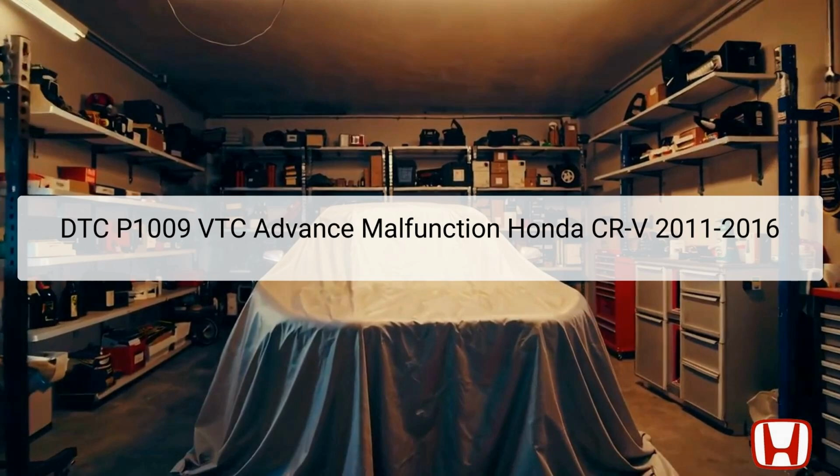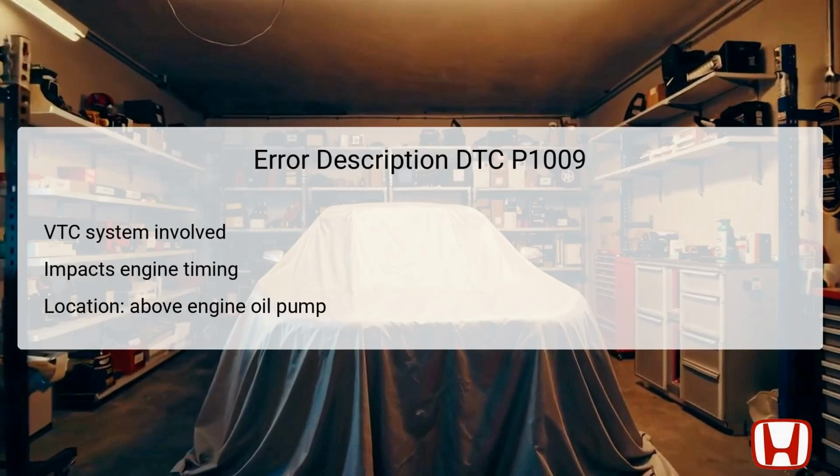The issue may stem from various components such as the VTC strainer, oil control valve, or actuator. A detailed troubleshooting guide must be followed to accurately diagnose and resolve the problem, ensuring smooth engine operation. The VTC system is essential for the function of the engine, particularly in optimizing the timing of gas intake and exhaust for better performance. The malfunction related to DTC P1009 usually involves the VTC strainer, VTC oil control valve, or the VTC actuator.